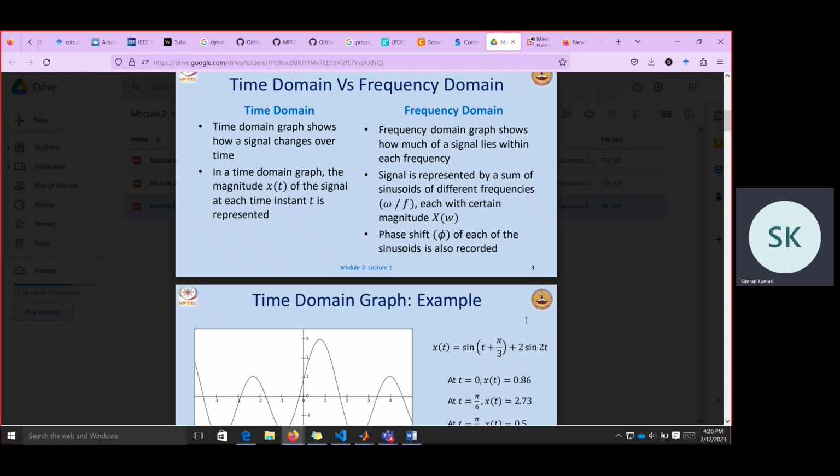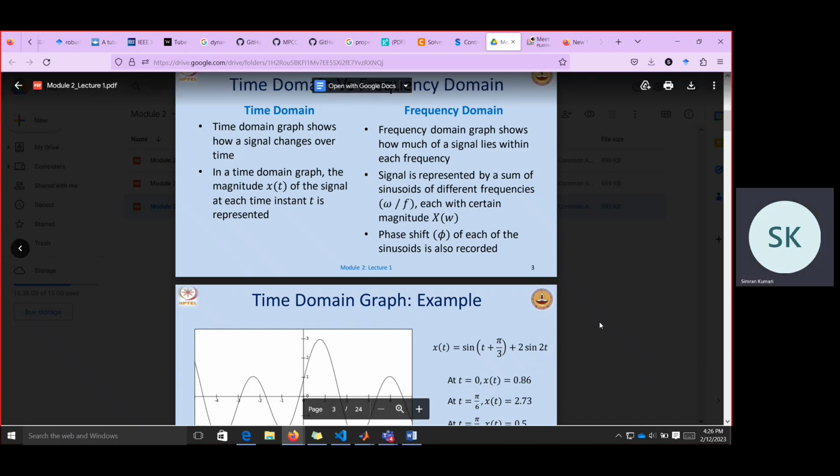For this sinusoidal signal, we know it will be of the same frequency. This will change the phase and amplitude. So from there we can say any signal, since we can represent it as a sum of sinusoidal signals, because it is a linear system, the output will also be the sum of the responses to the sinusoidal signals that we can apply.